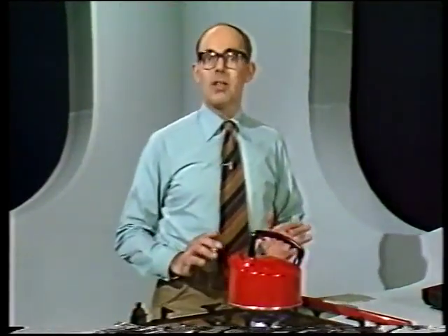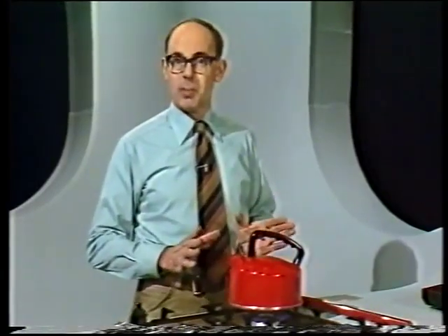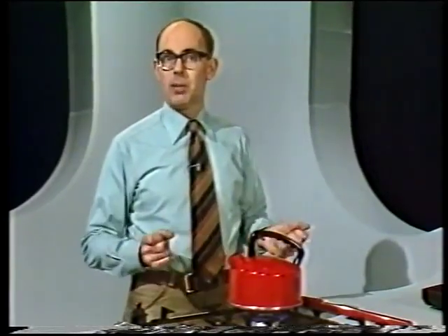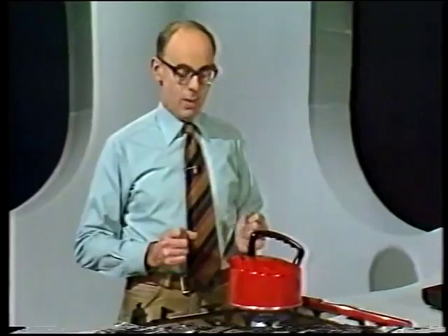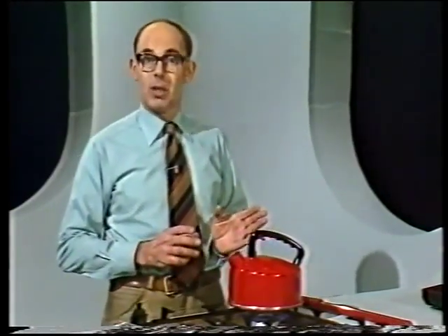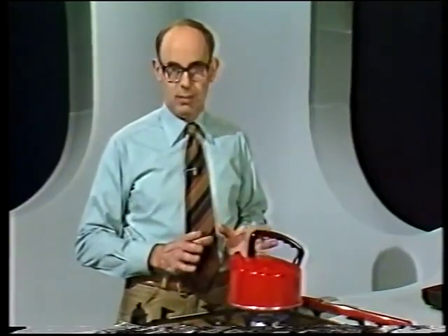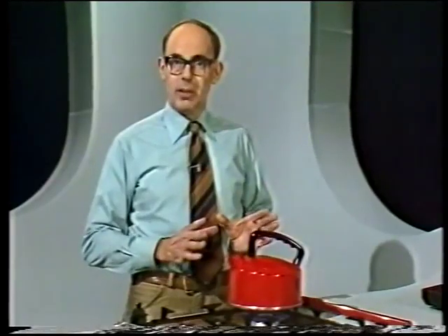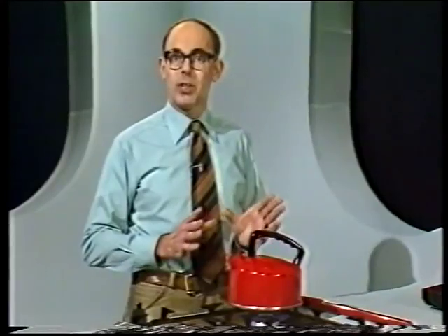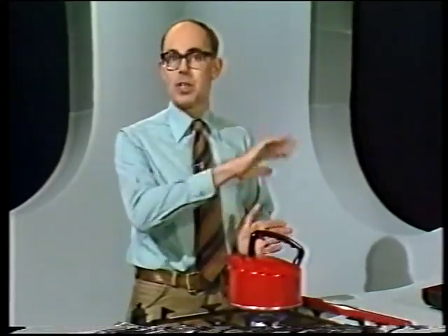But in this instance, there's also a change in the mass of the system, because water's lost as steam through the spout. So this could be a much more complicated system to deal with than simply heating cold water. An alternative thermodynamic system that could be used to describe this would be to define the boundary as enclosing all the water initially present in the kettle. In this way, the mass of water in the system is constant, but of course the system boundary would change shape and size as the kettle boiled, so that it always included all of the steam given off.